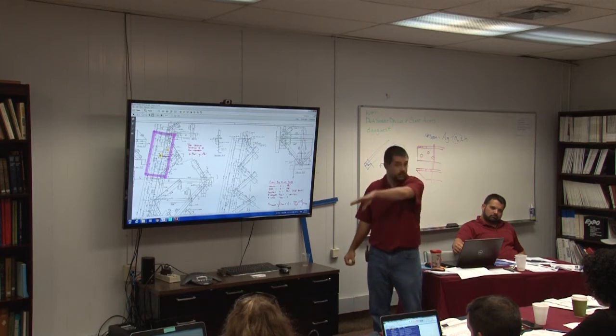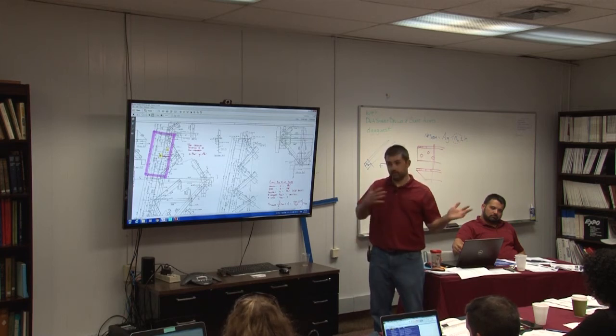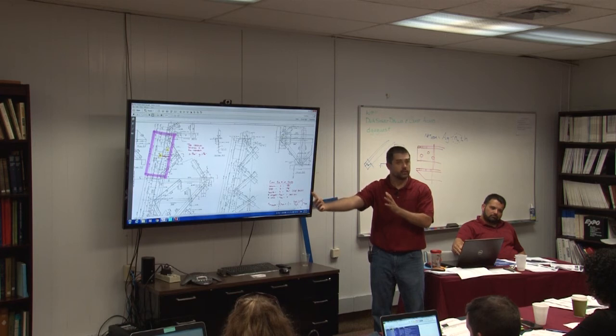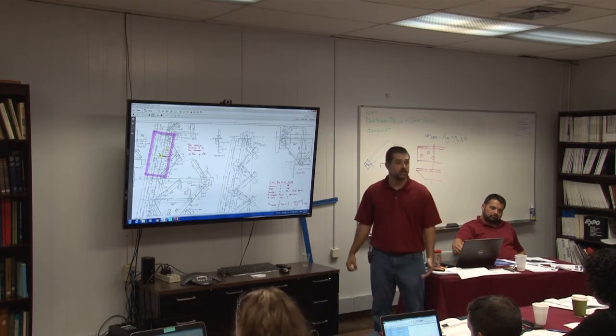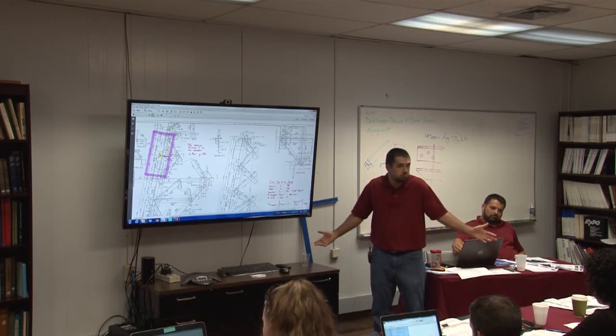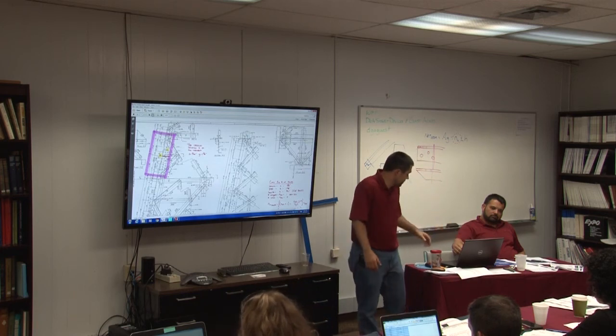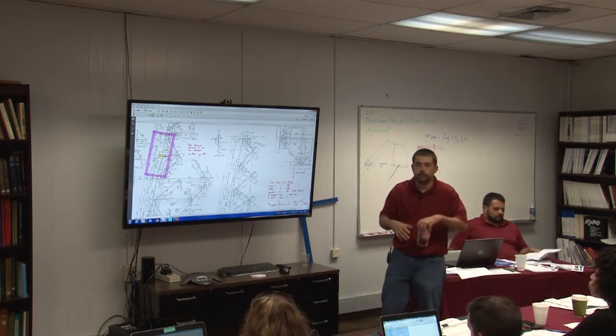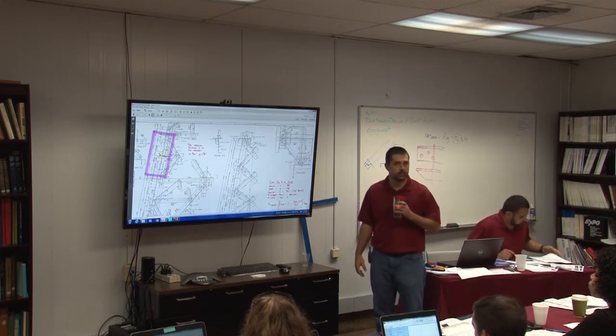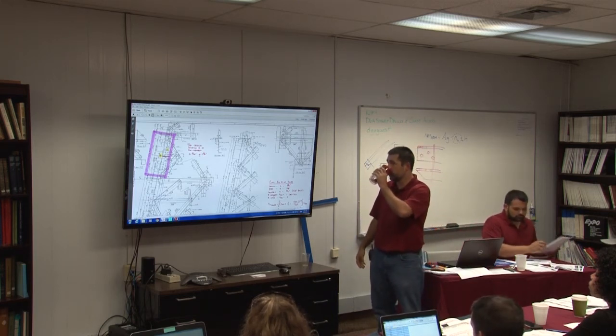So one of the options when you're looking at these old towers, especially if you're evaluating them under the old load cases, is: are you willing to back off that load factor to 1.2 or something else? And if it passes, then you're comfortable, right? But that's a risk decision that ultimately has to come from the owner. We can help define it for you, but we can't make those decisions.